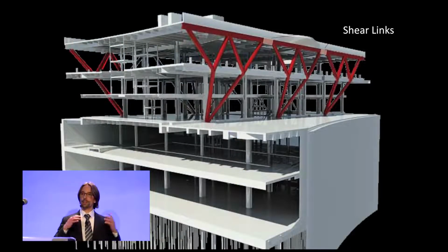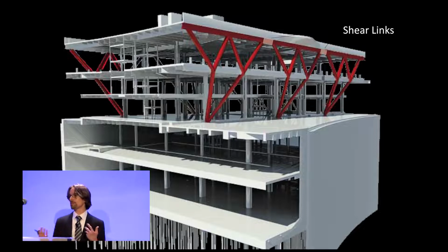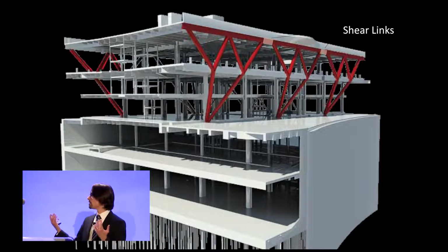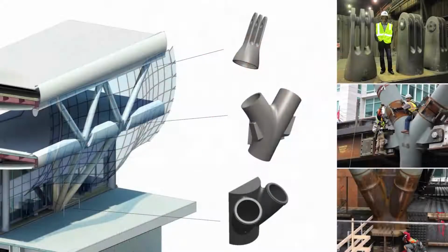Wrapping the perimeter of the Transbay Transit Center, as you all well know, is a structural steel frame. But that frame is actually part of the seismic force resisting system of that building. So when an earthquake strikes, all of the lateral forces of that structure have to transmit down through these trees that wrap the perimeter. And you can see it's architecturally exposed steel, visible to view in the finished condition. But because it's part of the seismic force resisting system, it's very heavily loaded. And so the designers decided to use castings at all of the key critical junction points.